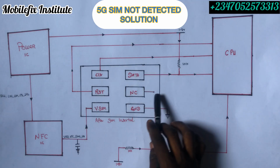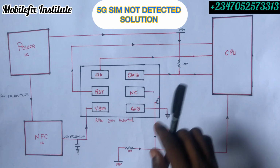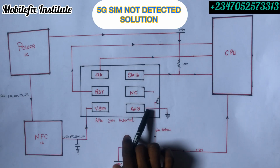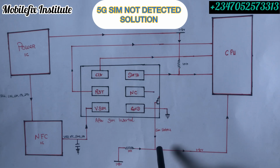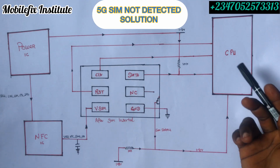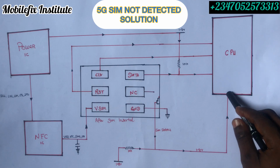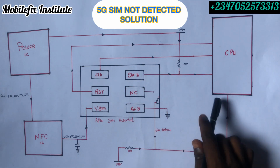This is the pin I'm talking about. When you have not inserted your SIM, you are going to have logic low, because this line is grounded. The CPU realizes that this line is ground, so it's not going to detect anything.